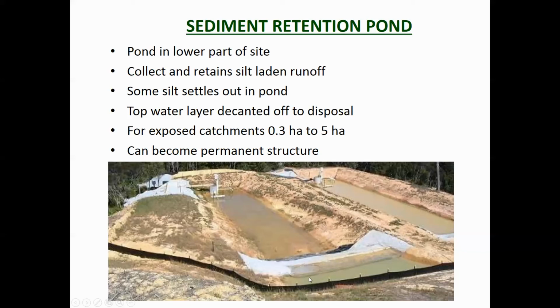You can see at present there's not much rain, so it's just sitting there. It's not going anywhere, and that increases the amount of sediment that's dropping out. But when the rain comes in, it'll rise up and go over the top of this. This needs to be level, and it needs to allow sheet flow into the second part here, which tidies it up a bit more. As the water flows along here, usually 3-4 days, the sediment that is left in the water will start dropping out as it moves along there.